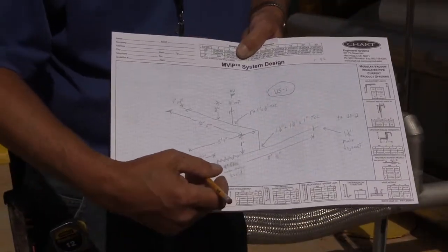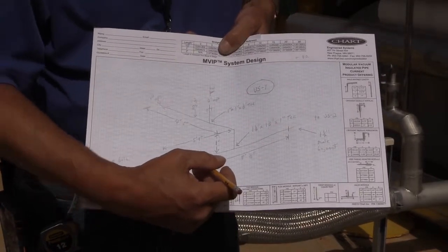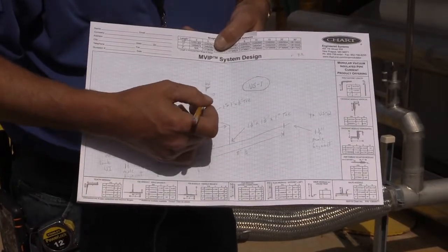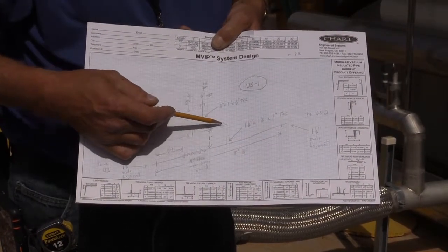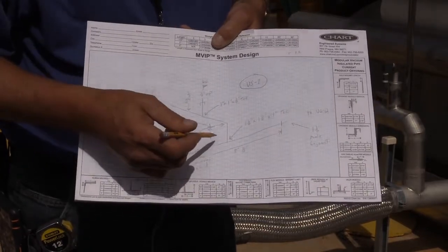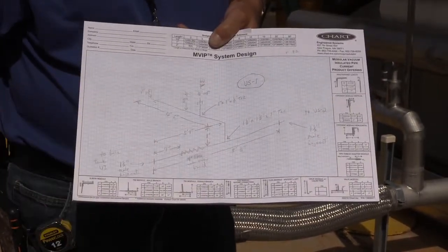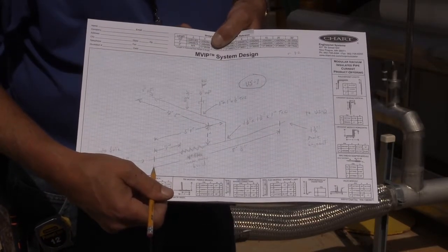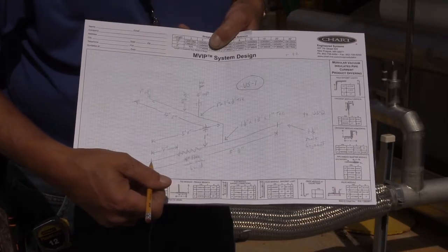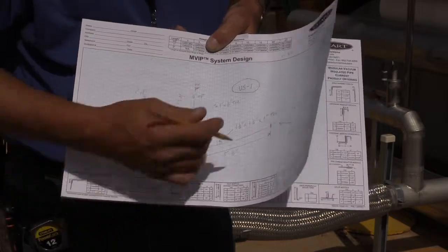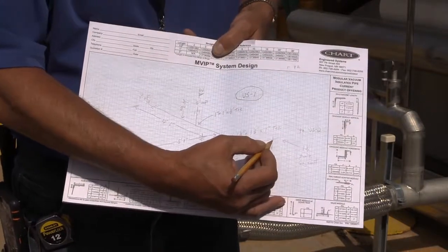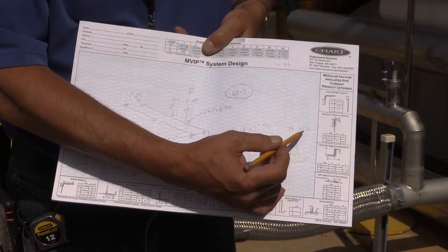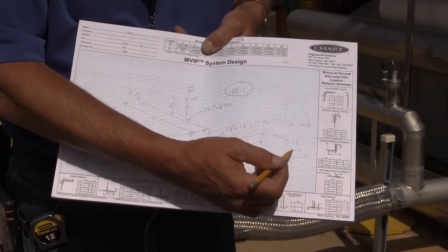These isometric drawings are typically drawn so you have a main header and then all of the appendages coming off of that main header and are drawn in a view where they make sense of how the section is actually laid out. So that said, within this we have an overall measurement of the length of the section from the male bayonet that's going to connect to the bulk tank, which goes over to this part right here, which is labeled 2VS2, which will be the second section we would measure and design.